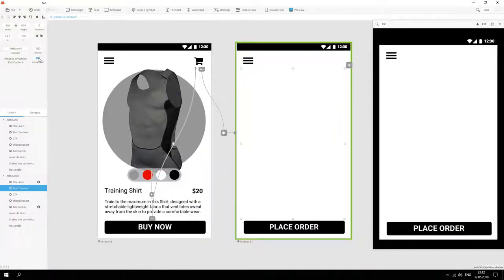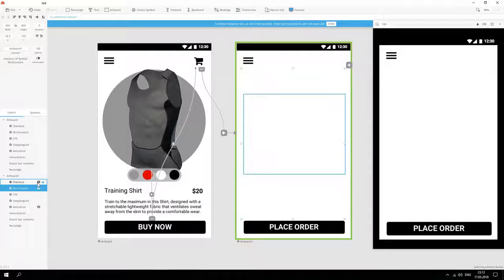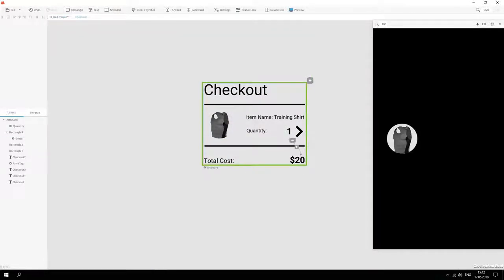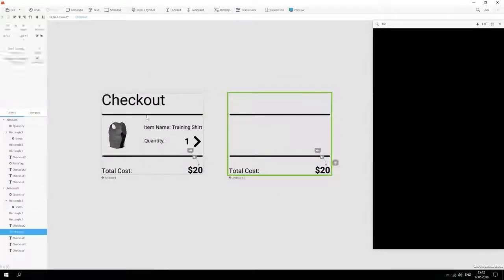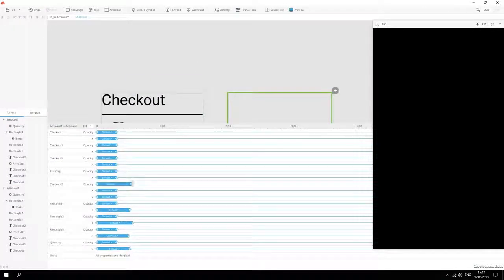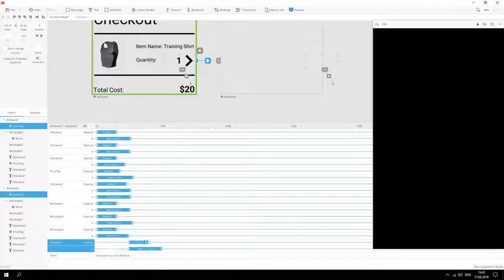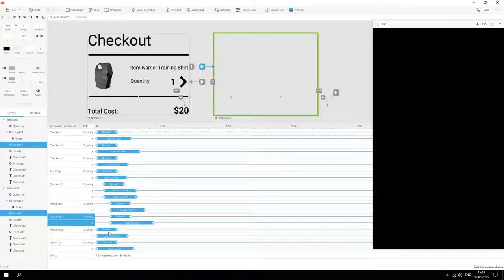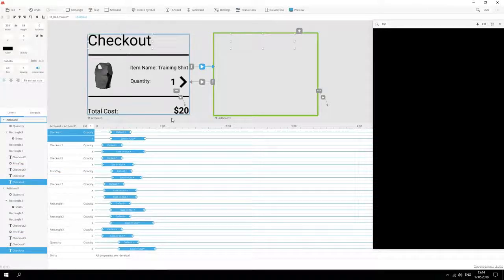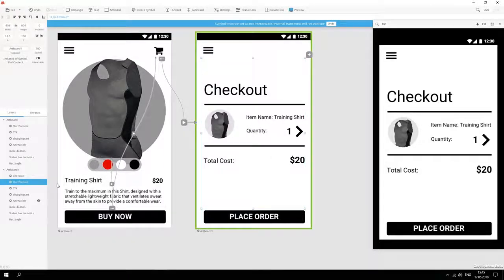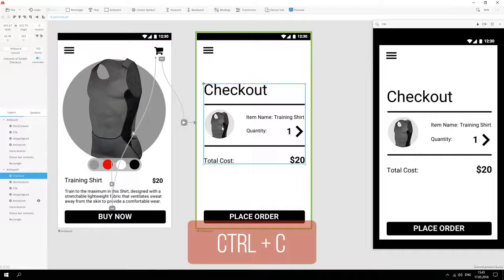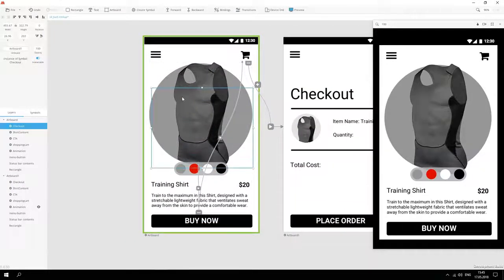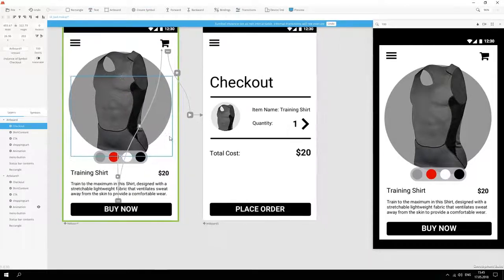Switch off the interactivity and hide it, then unhide the checkout symbol. Now go to the second artboard, get inside the checkout symbol, and do the same with this one. Copy the artboard, change the opacity, this time move the objects to the right instead of left. Change the default transitions and exit the symbol. Select the checkout symbol, copy it to the first artboard and select artboard 1 from the drop-down as well. Also turn off the interactivity for this instance.